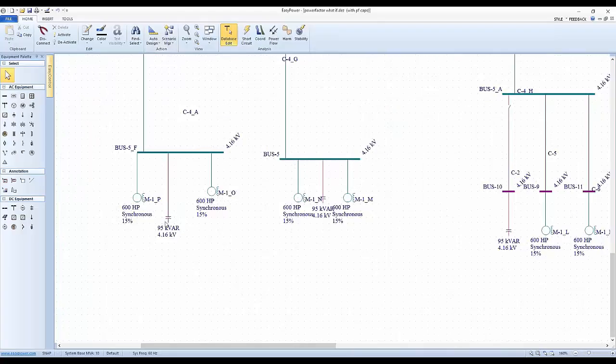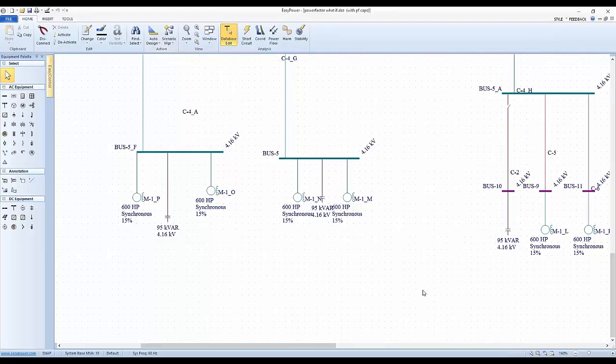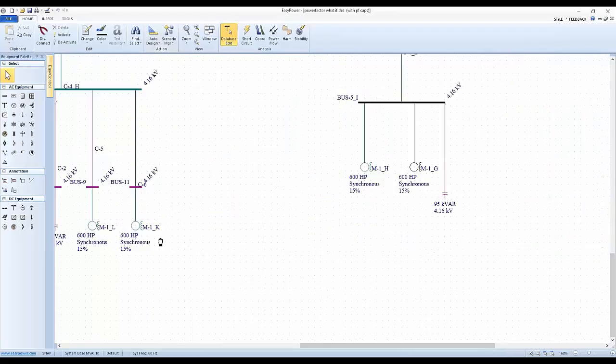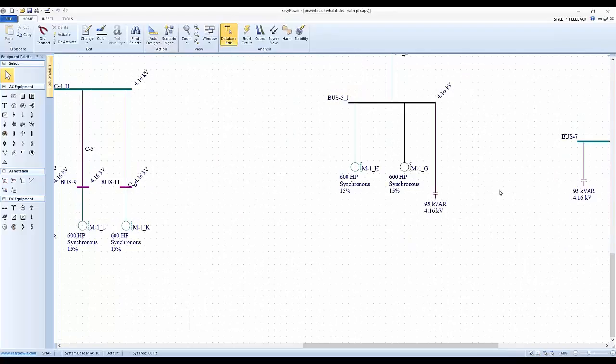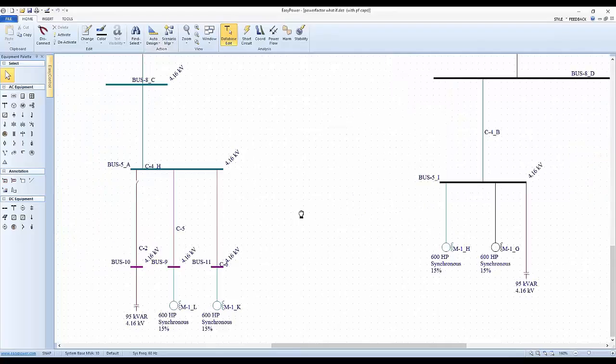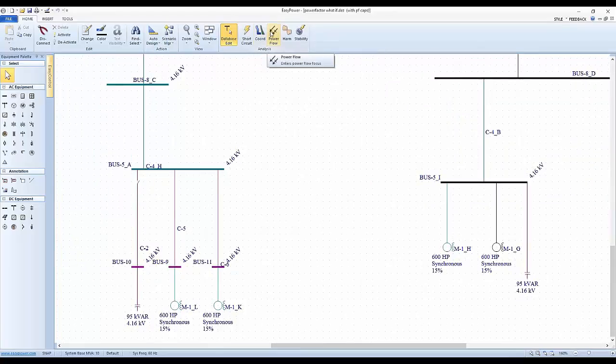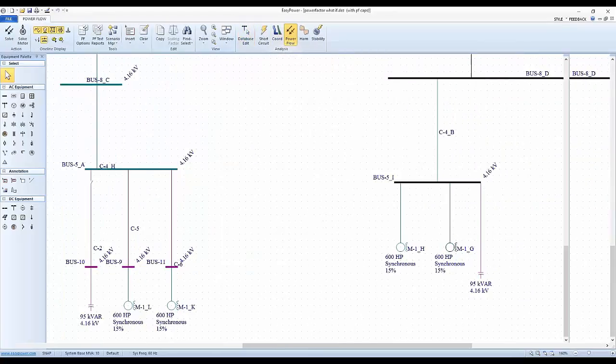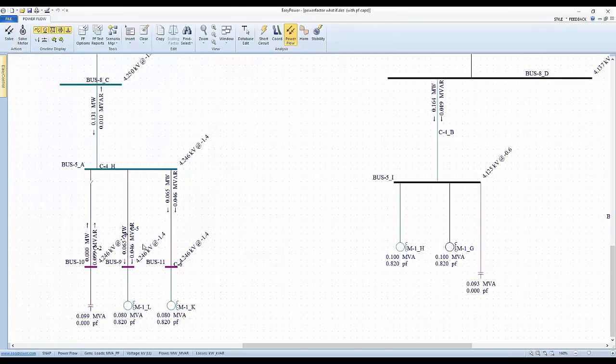And so where we had a 98 kVAR inductive reactive power we have to compensate, we're going to put in a 95 kVAR capacitor in each one of these. And on the right-hand side, it seems like I went with a little bit higher. Oh, I went 95 kVAR across the board. Okay, let's go back to power factor. Solve the equations.